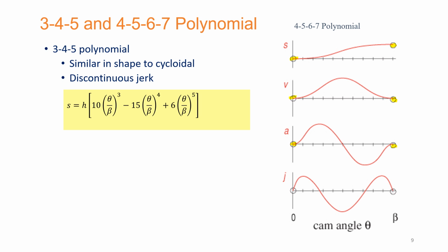So now for the very first time in case of J, we have added 0 initial condition for the starting value and 0 once again jerk value once the motion has been completed, once the rise has been completed. So this is needed to be incorporated.